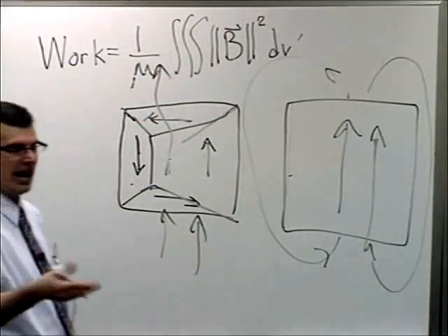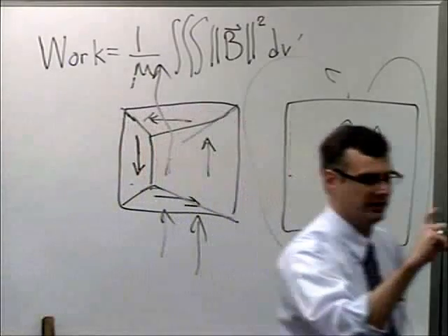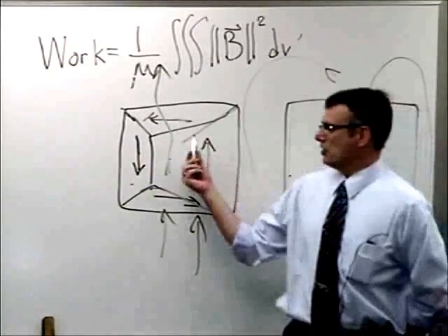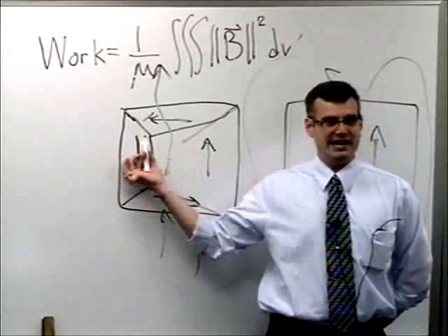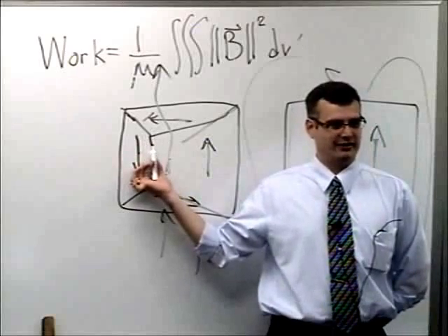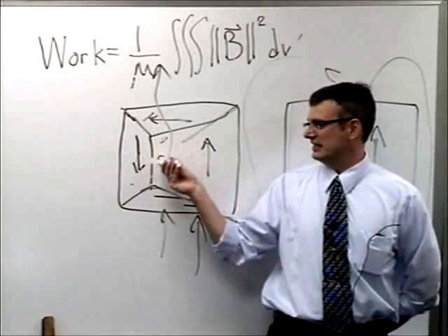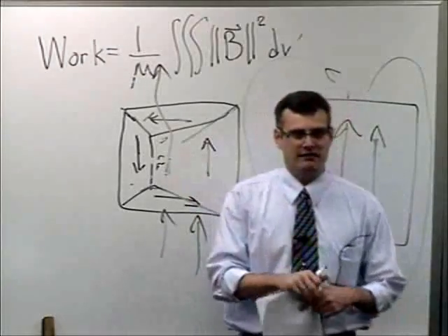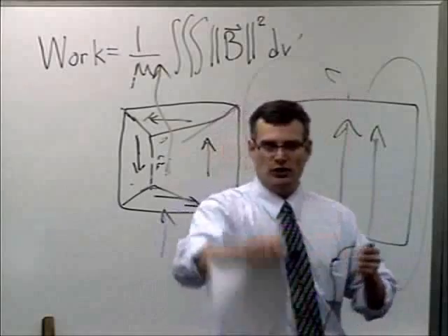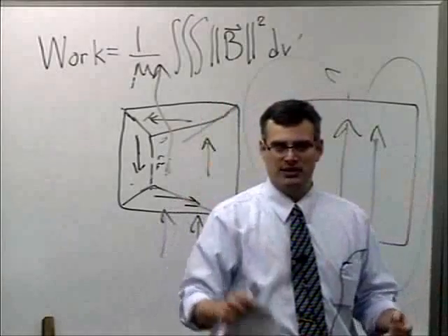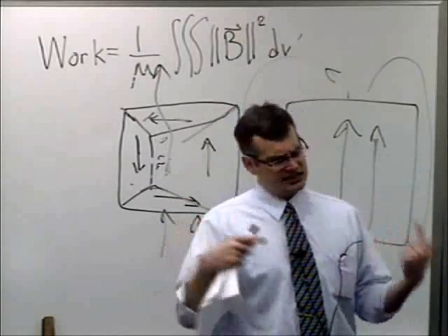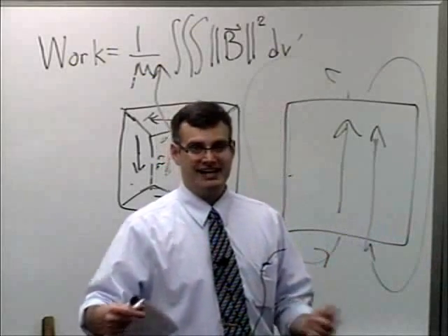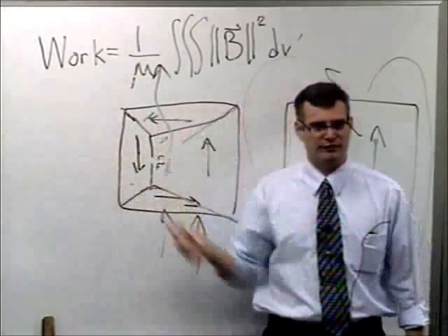And so you still get the high mu sub r behavior, even if you can't observe the permanent magnetic moment. In fact, there are often crystalline impurities in here that once you move the domain wall, you pin it. It can't move back for whatever reason. There could be some impurities in here that keep it from forming back in its original position. And so this is how, if you ever take a piece of steel and you stroke it with a magnet, or you heat it up and you cool it in the presence of a magnetic field, you can turn something that didn't have a permanent magnetic dipole moment into something that does. And again, this is just another manifestation of this peculiar ferromagnetic property.